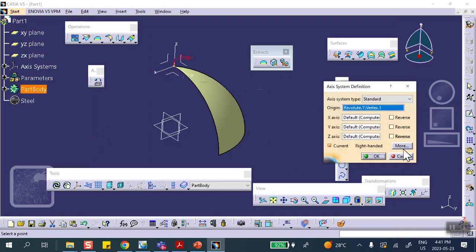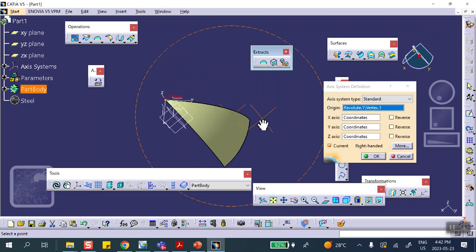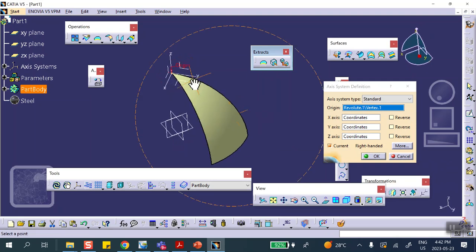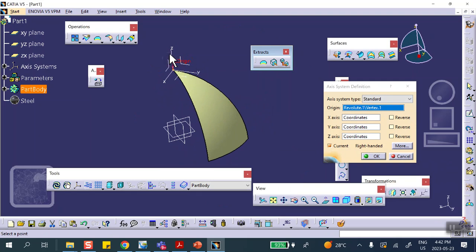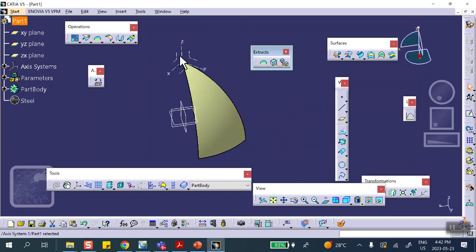You click on it, the origin is up there, and you say okay, but I want to rotate this thing more by 45 degrees. We did this in class. So that would be 0.707, cosine of 45 degrees. And this will also be 0.707, sine of 45 degrees. At the end of the day, you have to rotate this thing because now you see that this edge is in the YZ plane. Good. And I don't want this to be the current coordinate system. So uncheck this so that later on when you think about coordinates x, y, z, it's not with respect to this. It's with respect to the global one.